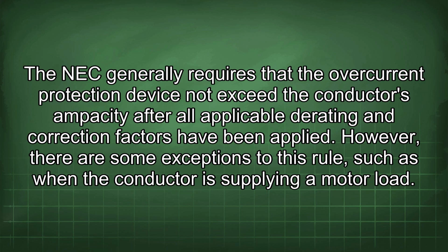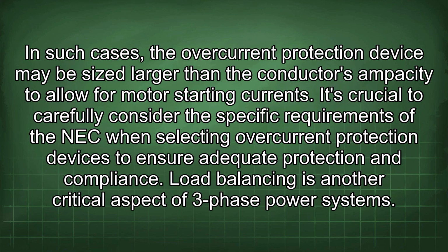factors have been applied. However, there are some exceptions to this rule, such as when the conductor is supplying a motor load. In such cases, the overcurrent protection device may be sized larger than the conductor's ampacity to allow for motor starting currents. It's crucial to carefully consider the specific requirements of the NEC when selecting overcurrent protection devices to ensure adequate protection and compliance.